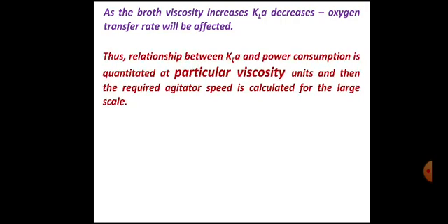So what is important here? The important thing is that the relationship between KLA and power consumption has to be quantitated at a particular viscosity of the fermentation broth. This is very important. So the relationship between KLA and power consumption is quantitated at particular viscosity units, and then the required agitator speed is calculated for the large scale.